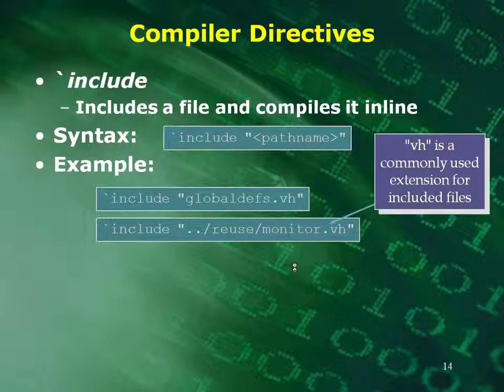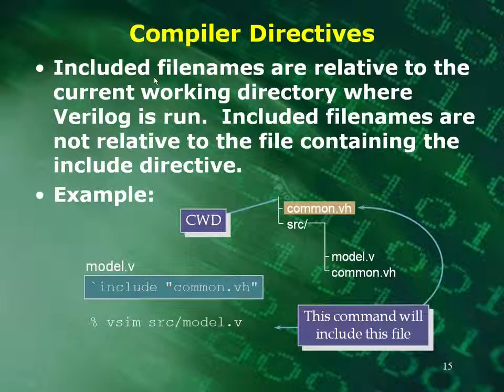One thing to remember is that included file names are relative to the current working directory where Verilog is run. Included file names are not relative to the file containing the include directive. So let's say that we had changed our working directory to right here, and I had a file called model.v, and it said include common.vh.